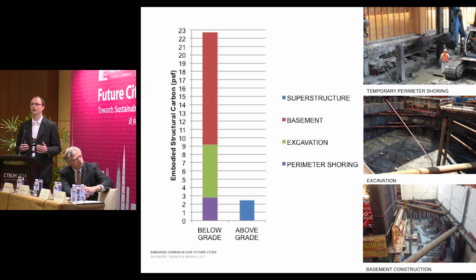Our contractors are extremely efficient in above-grade work. This had a 5-day floor-to-floor cycle, mostly because of the volume of concrete. Some buildings get down to 3 days per floor. Very, very efficient. But I don't think we're as efficient as we need to be below grade. I don't think we're as efficient with materials or in our construction processes as we need to be.